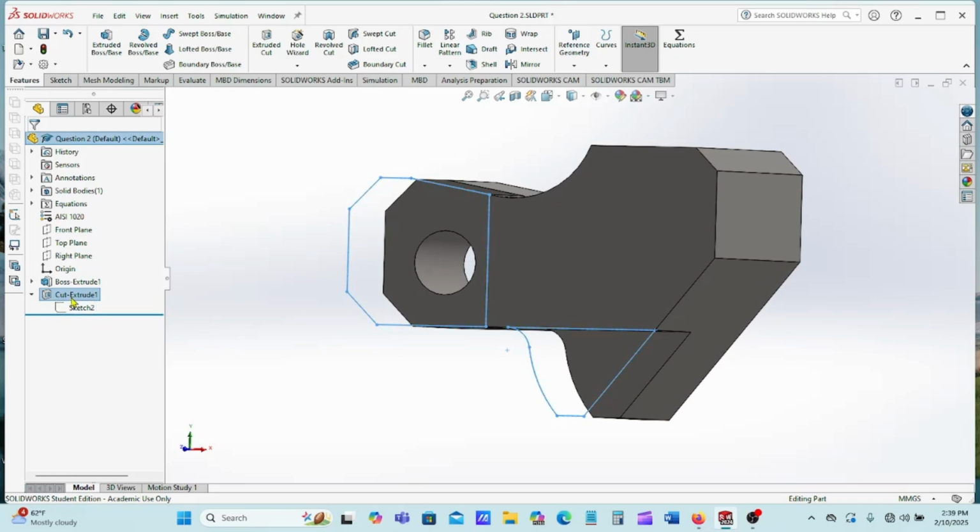So if I open up that cut extrude, I click on my sketch here, and it brings up a dialog box, and I want to click on the eyeball, and I'm going to do that twice because it will hide that drawing so I don't have to look at it. All right, now we have to draw in a circle and do an extrude cut.